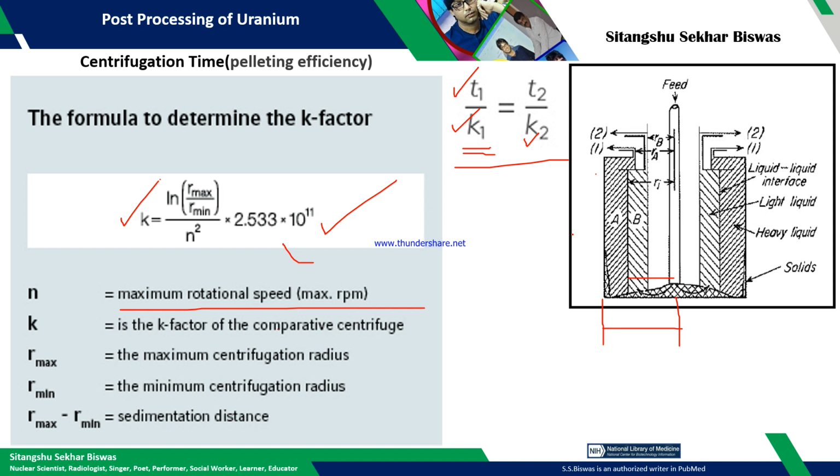So this is the very basics of centrifuge, but you may think that it is very easy, but the design is very tricky, because the motor, the prime mover, should be designed for very high RPM. Nowadays BLDC motors have come, and you need one inverter. The power frequency of the inverter should be very high, and it is to be switched at very high frequency.